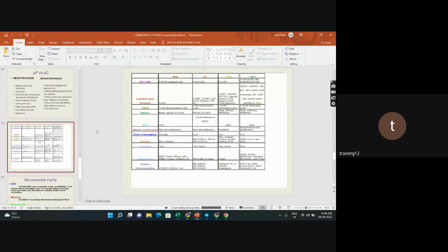And I2C is Inter-Integrated Circuit protocol. It is also synchronous, multi-controller, multi-target, packet switched. This is a serial communication protocol that can connect low-speed devices. It is mainly master-slave communication in which we can connect and control multiple slaves from a single master.